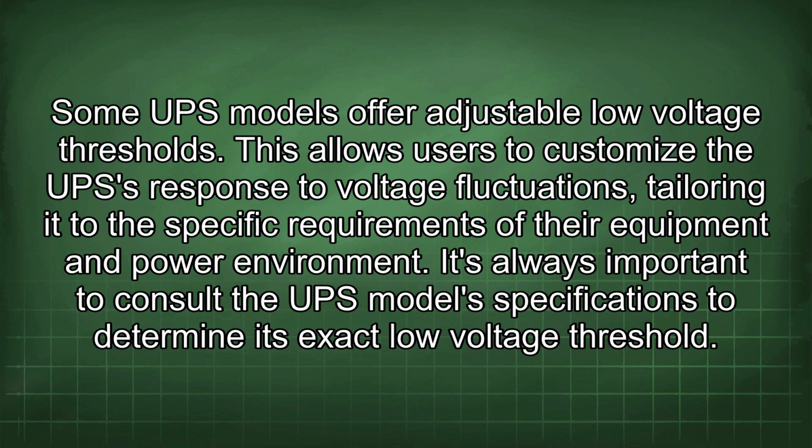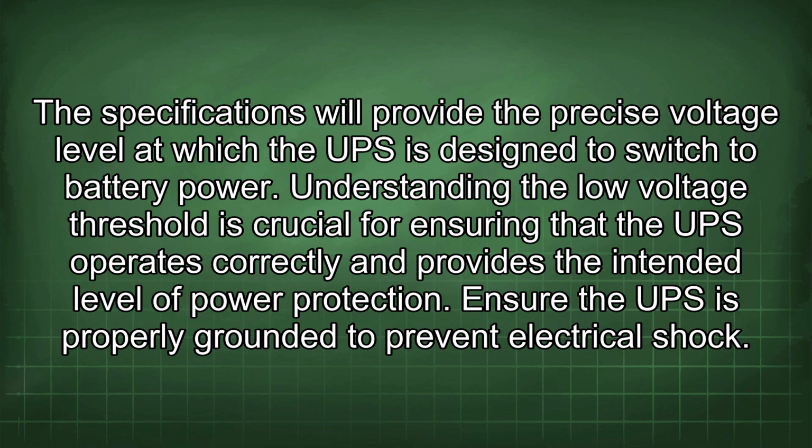This allows users to customize the UPS response to voltage fluctuations, tailoring it to the specific requirements of their equipment and power environment. It's always important to consult the UPS model specifications to determine its exact low voltage threshold. The specifications will provide the precise voltage level at which the UPS is designed to switch to battery power.